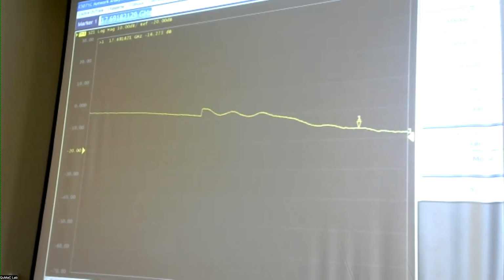close to like 16 or 18 dB of loss in this cable, this nice cable, at 20 gigahertz. It's quite lossy. It's nearly 20 dB. It's like a factor of 100 in power. So these are things in practice you have to be careful about in an experiment, that you have very long cables and at high frequency cables also. So the semi-rigid variety, the ones I had shown, which are the solid core, they will have less loss than these particular type of cables.